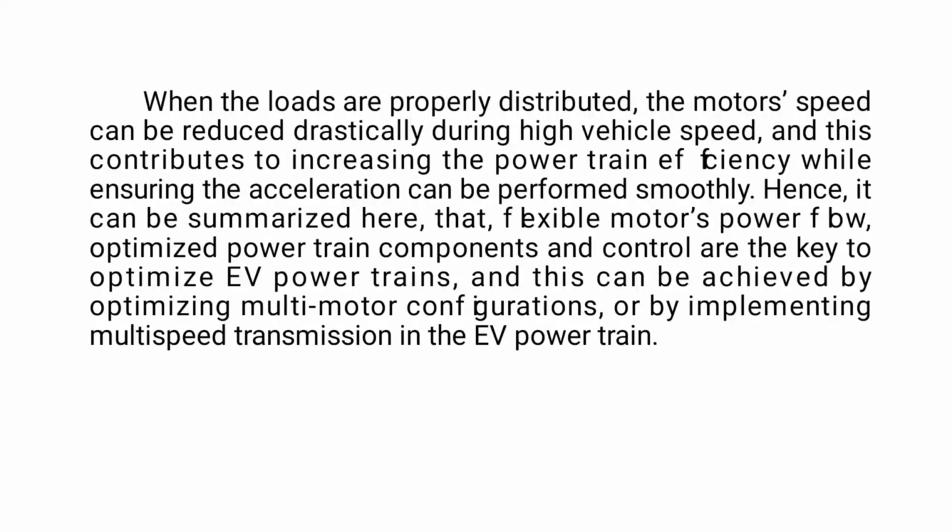When the loads are properly distributed, the motor's speed can be reduced drastically during high vehicle speed, and that contributes to increasing the powertrain efficiency while ensuring the acceleration can be performed smoothly. In electric powertrains, this can be achieved by optimizing multi-motor configuration or by implementing multi-speed transmission in the electric vehicle powertrain.